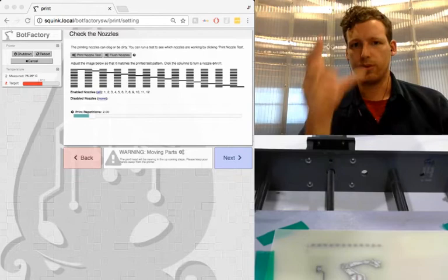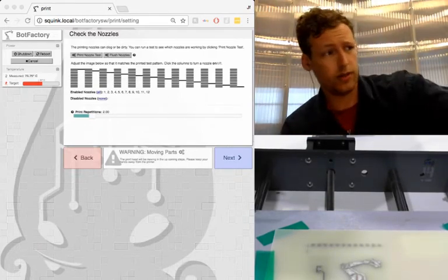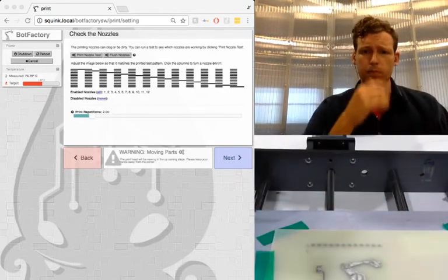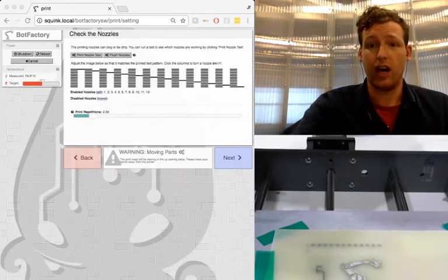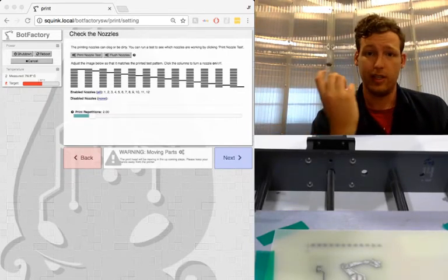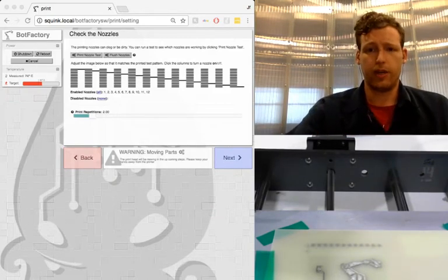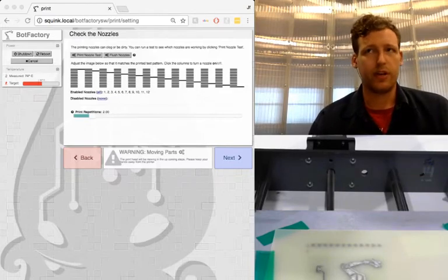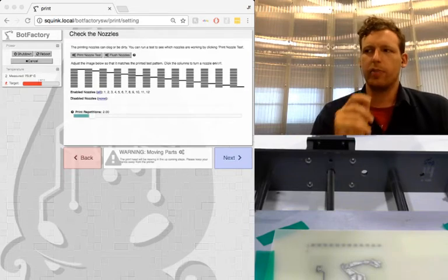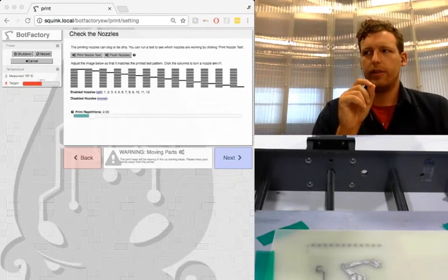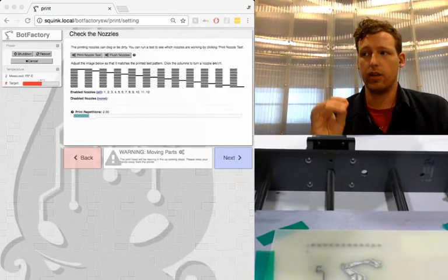Now, those heaters that create bubbles in the chamber that jet out the material can get covered with this insulating ink. So we recommend that you use a small syringe of IPA, isopropyl alcohol, not the deionized water, important to note, and you apply a little bit on there and let it sit. I find that immediately applying it and then jetting it doesn't really clean it properly. A little bit and leaving it for 10 minutes seems to do the trick. Cleans the nozzles very nicely.